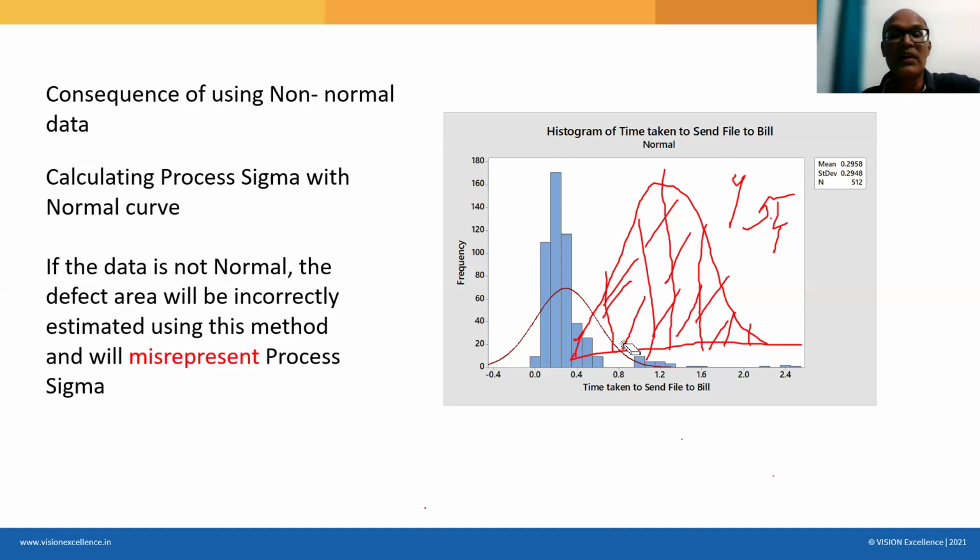Instead, you collect a sample and use it to estimate that yes, you are in a very good process with reference to specification, right? So here we are talking about two things: one is the specification limit, another is our process variation, right? With reference to specification, where you are standing, that is the purpose of process capability: collecting the sample from a lot and estimating the capability. This is ultimately the purpose of CP, CPK and PP, PPK.